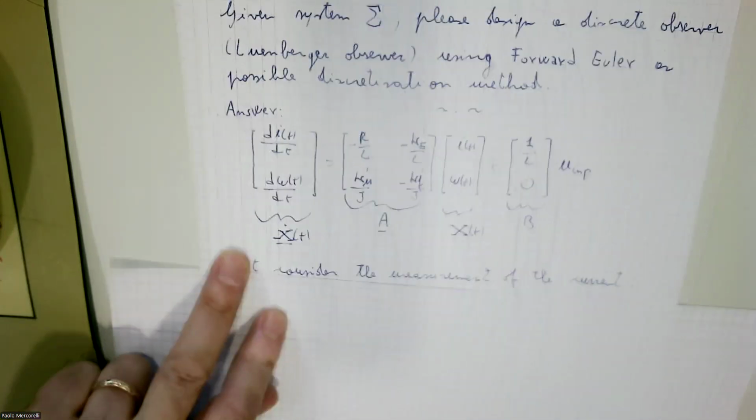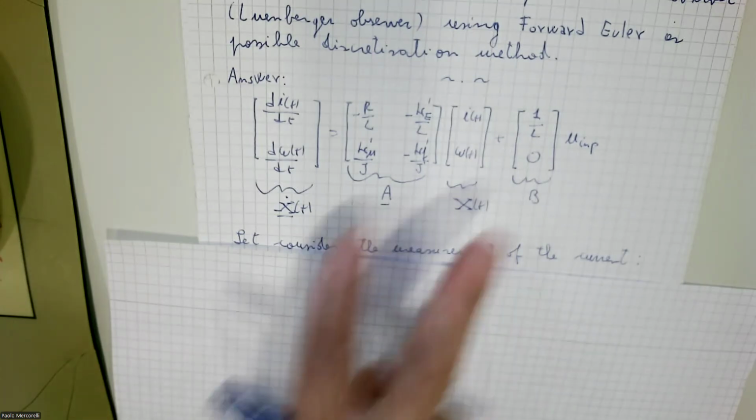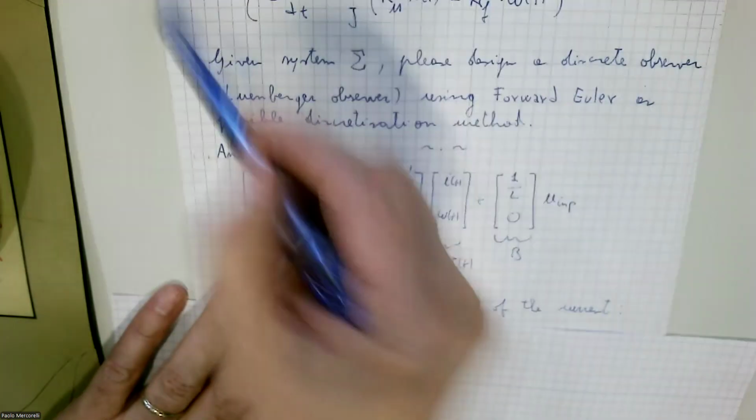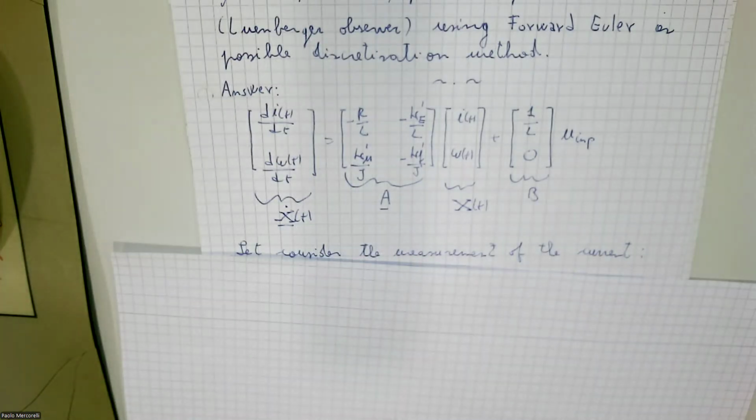Why is this form suitable? It's an advantage because at least when we are working with a linear system, we can use the algebra of the matrices, but not only that, the microcontroller can work very well with tables. Tables are matrices, a table is a vector. It's really suitable, and a big advantage for the microcontroller. Of course, if you have some nonlinearity, this representation has limits, or at least we cannot directly use the algebra of the matrices.